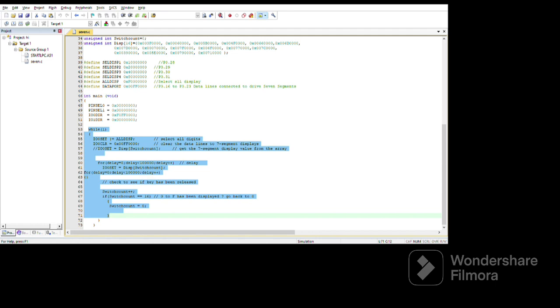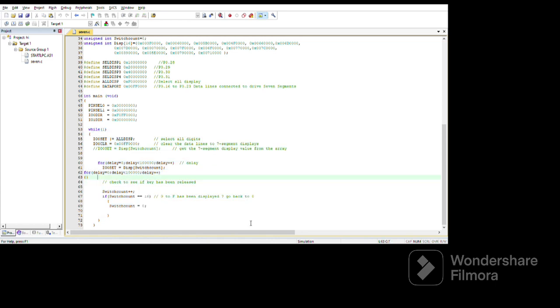We'll divide the counter value into individual digits and extract each digit from the counter value. To achieve multiplexing, we'll cycle through each digit by turning on the corresponding segments for that digit and keeping the other segments turned off.